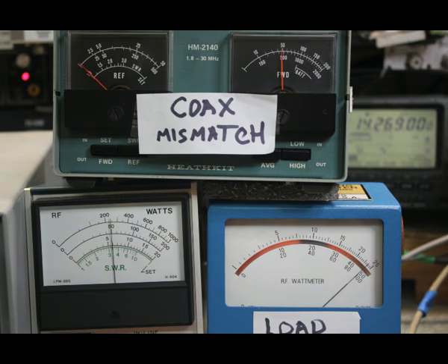The meter on the lower left is the LPM 885 meter, and we see that it's registering 50 watts of power from the ICOM 746 into the matching network at the transmitter end. That network's adjusted for a 1-to-1 SWR, so it's just kind of like a passive network.